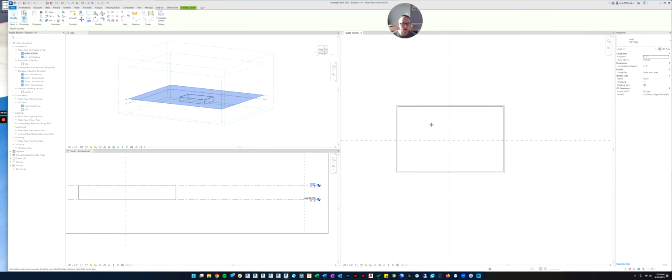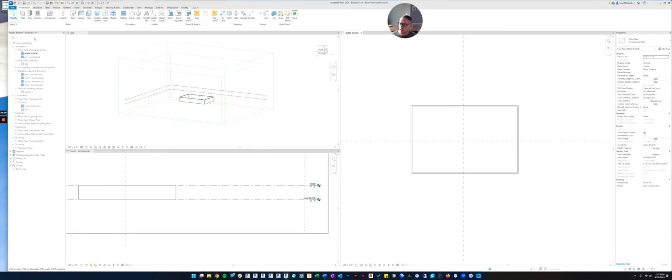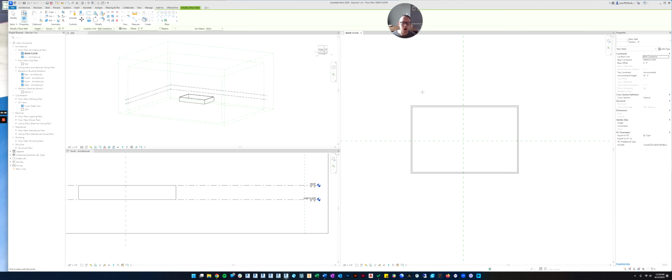And now let's say we want to divide this. Let's put some rooms inside. So I go back to the wall command. Now, before I draw a wall, let's look at what's happening. Before you draw the wall, you can still see what properties the wall that you're about to draw will have. And you can see if you go to the top constraint that it's unconnected. Let's just change that right now to roof. That way I don't have to change the walls after I draw them. I can change it before I draw them.